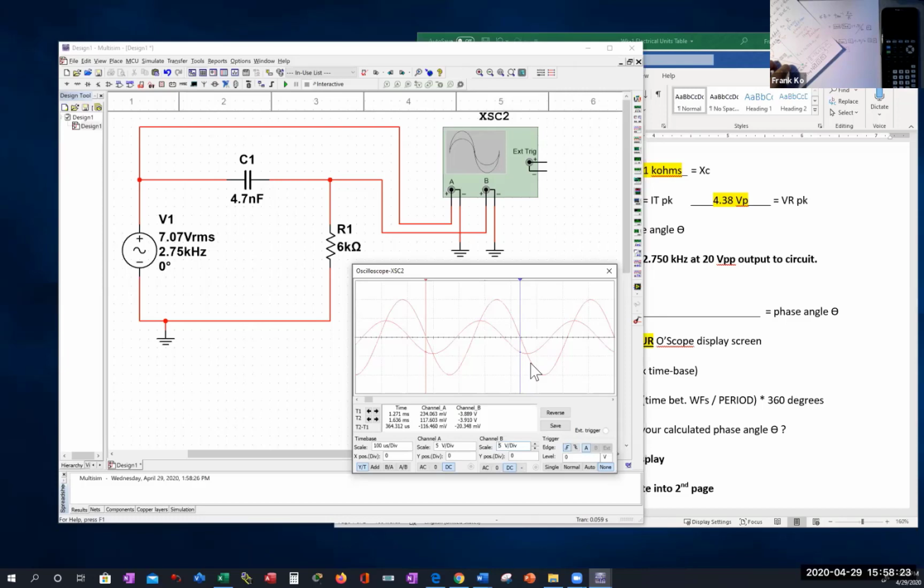Do you all feel comfortable and happy with that? Or some of you might prefer the starting point of a waveform. Let's go here, and then where the waveform starts to repeat itself. Maybe that's a little more uniform with the discussions we've had in the past. So take a look at the larger waveform. This is where it starts from the zero line, goes positive, goes to here, switches over to the negative, comes back over, and this is where it starts to repeat itself. Are we in agreement that I have one cycle between these two cursors? Done. What is my time between these two cursors?